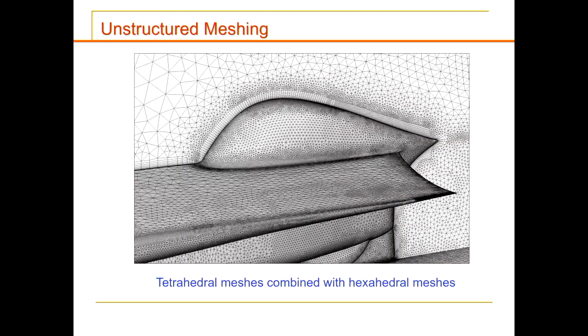The other alternative is unstructured meshing, which is basically called triangular meshing. Now, triangular meshes tend to be able to conform to the design of your system, of your geometry, much easier. But with tetrahedral meshing, or what you call triangular meshing, sometimes you are unable to control the density. Okay? In terms of density, you tend to use fewer elements in structured meshing compared to tetrahedral meshing.